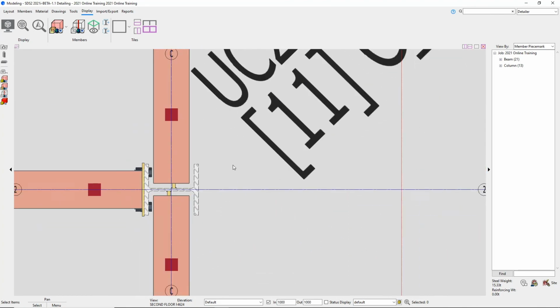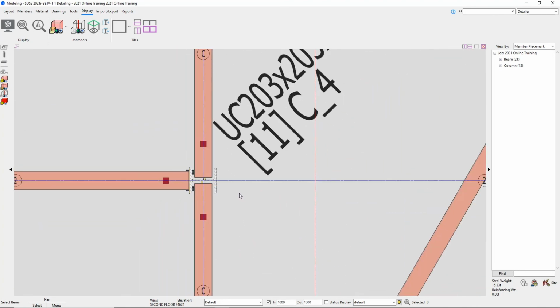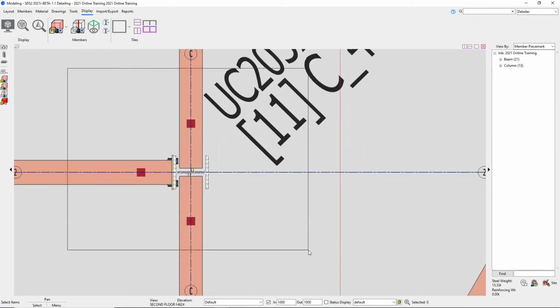Another thing to look at here is selecting with your bounding boxes. So one thing to show here is if I would go from right to left, so if I start over here and I left click and I go from my right to my left, we see we get a dotted line box.